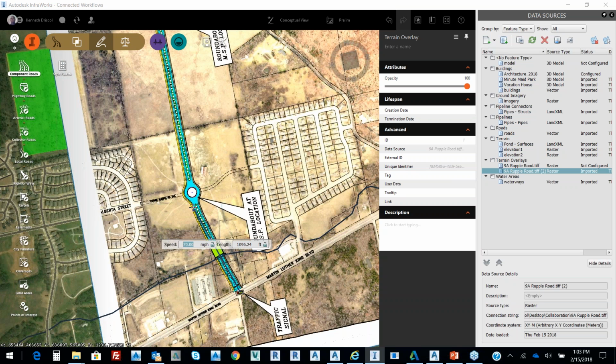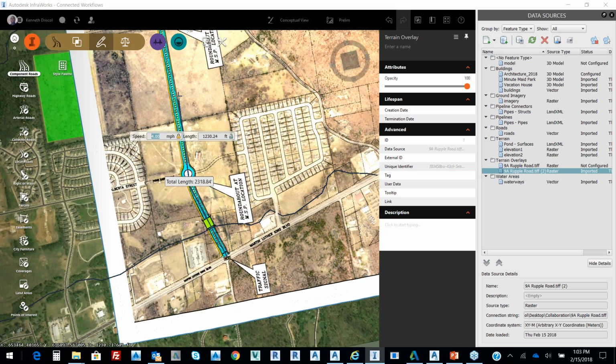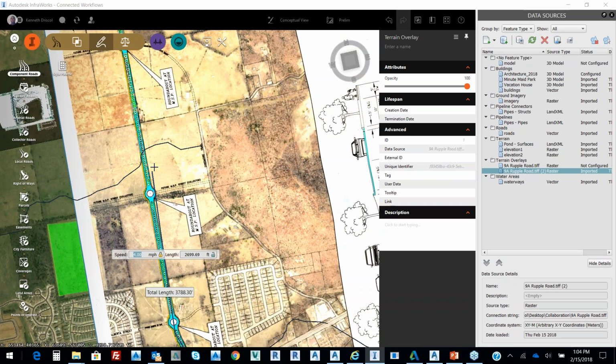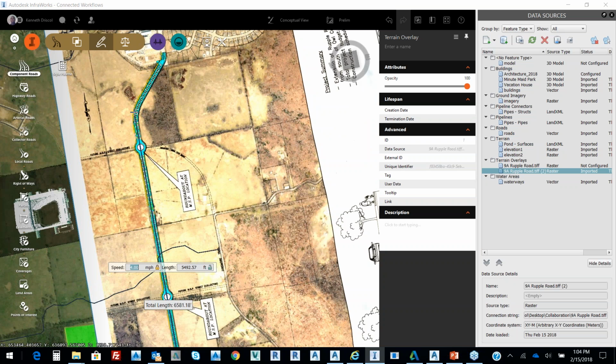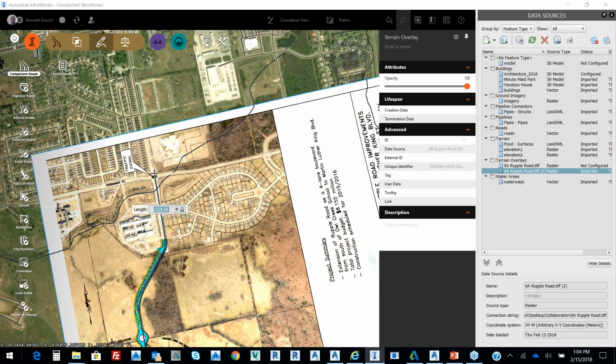And you can see it's set for 70 miles an hour, but we can make that 40 miles an hour, and it changes my curve radius. So it's based upon AASHTO standards, and I'll just come straight through here, and I'll just pick this point, and I'm just gonna go a little bit quicker, and then I'm gonna come up, and I'm gonna double pick this point right here.